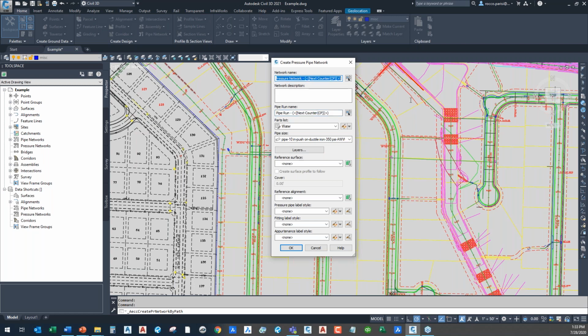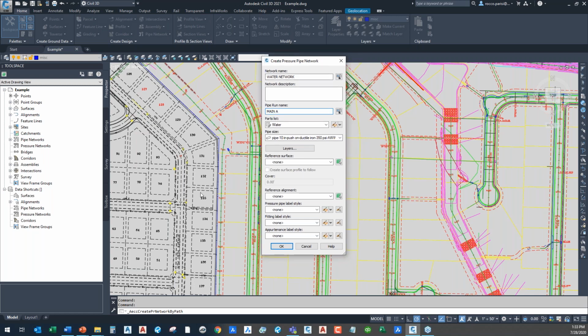If we were to define this, this is just our water network, the overall water network. As part of that, I can have different mains. So this is main A. If I have different water mains, different pipe connections, existing main, new main, proposed main A, B, C, D, whatever I have, I can name and run those separately. And you'll see when we get a little further along that this can play a big part in what you're doing.